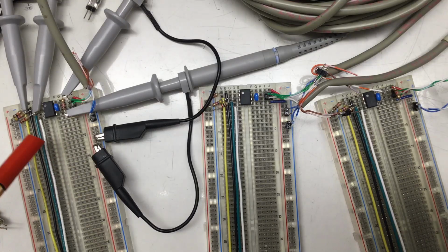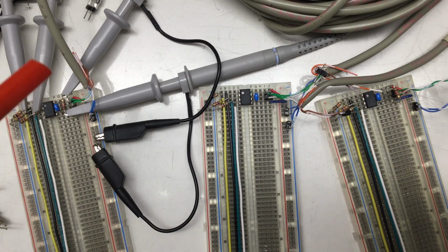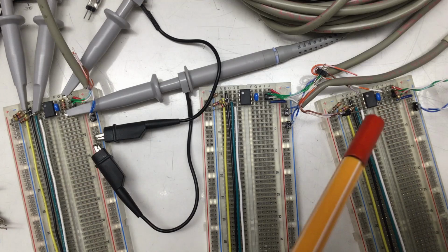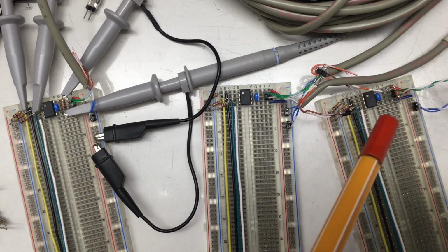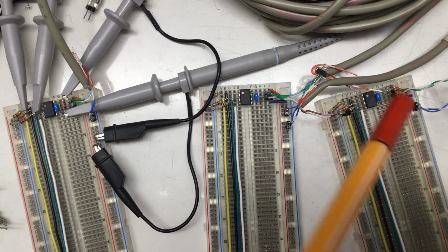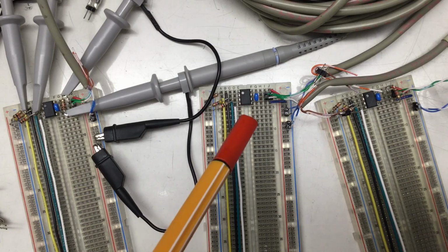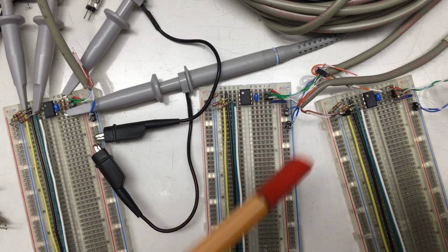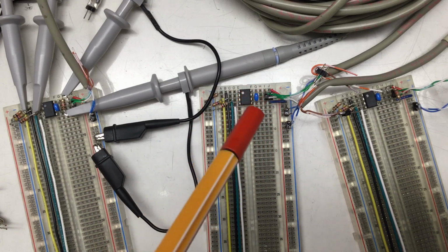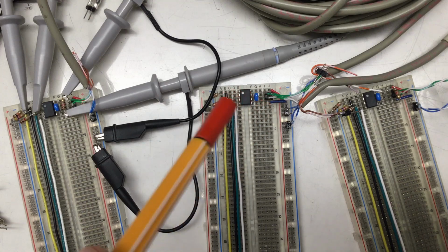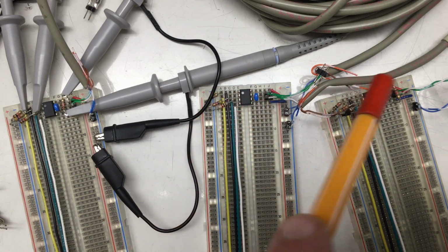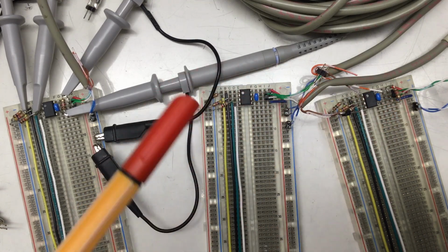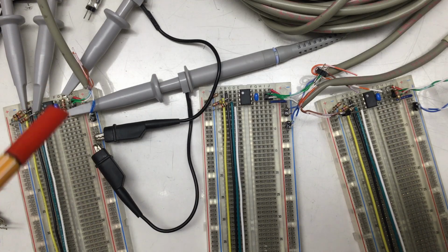In our new setup, the master is still connected to one end of the bus, but now the other end of the bus ends at our new second slave, while our old first slave is somewhere in the middle. Consequently, I moved the termination resistor from the first slave to the second slave. And of course, we keep that termination resistor here on the master.